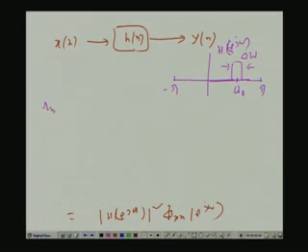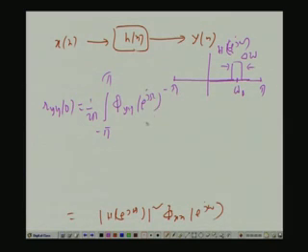So, what is r_yy[0] as before? This will be 1 over 2 pi times the integral from minus pi to pi of phi_yy e to the power j omega, d omega, e to the power j omega, but this integral is localized only around omega naught within a band of delta omega. Okay. And filter height is say 1.